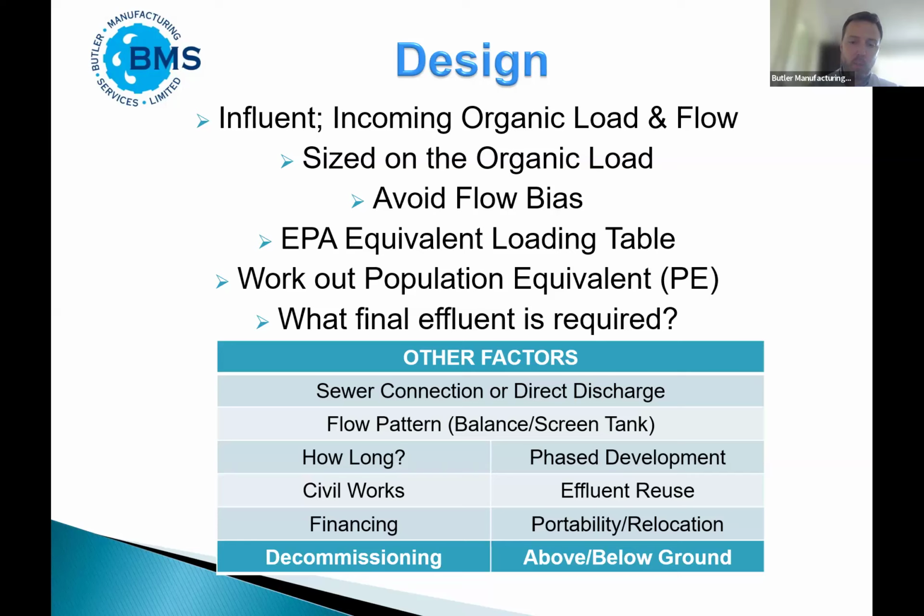So say for example in a hotel or a housing development with a lot of commuting, it would fill up rapidly in the evening, and then it would actually pump down at night, spreading the flow to the sewage treatment plant, which typically improves flow a lot. And these tanks can also be used with the baffle and macerator pumps to screen out non-soluble solids.